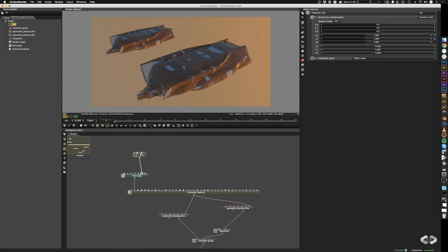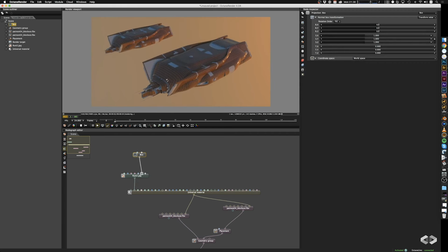It's applied in a box projection mode, and we can also tell it to use world space. So ignore whatever scale was set for the different elements, and just use the world coordinates to project this on here. And then we have here R for rotation, S for scale, T for transform. This one is locked right now into a uniform scale. That usually makes sense unless you're going for some very funky effects, and then you can disconnect it. But so now when we move one, we move all of them. And then you can see how we're setting a different kind of scale for our object.